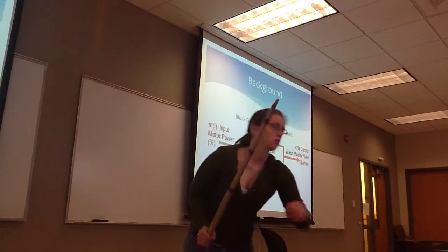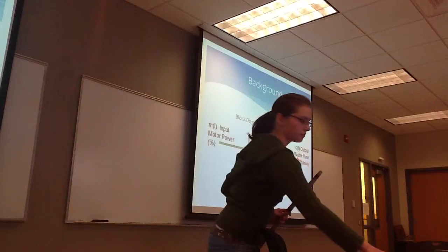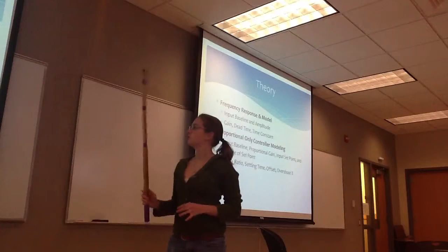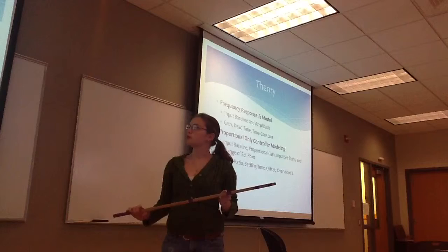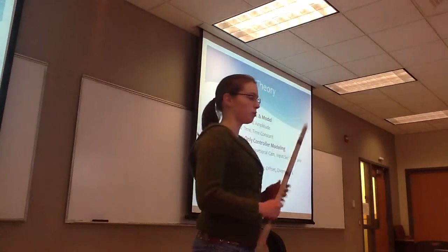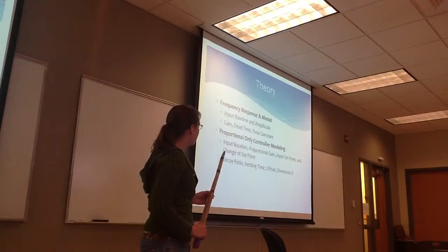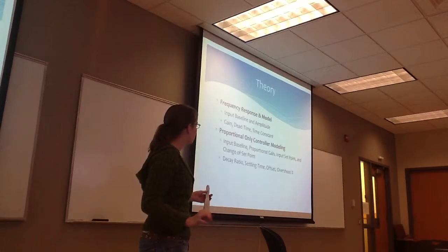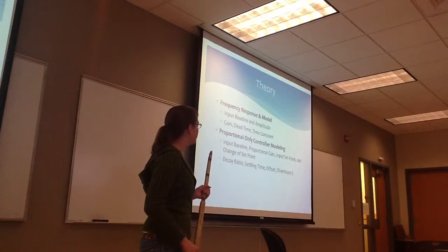And this is a block diagram of the filter wash system. The theory behind this is with the frequency response, you'll input a baseline and an amplitude, and you'll get your gain, dead time, and time constant. For proportional only, you will have an input of a baseline and proportional gain, set point, and change in set point, and you'll get decay ratio, settling time, offset, and overshoot.